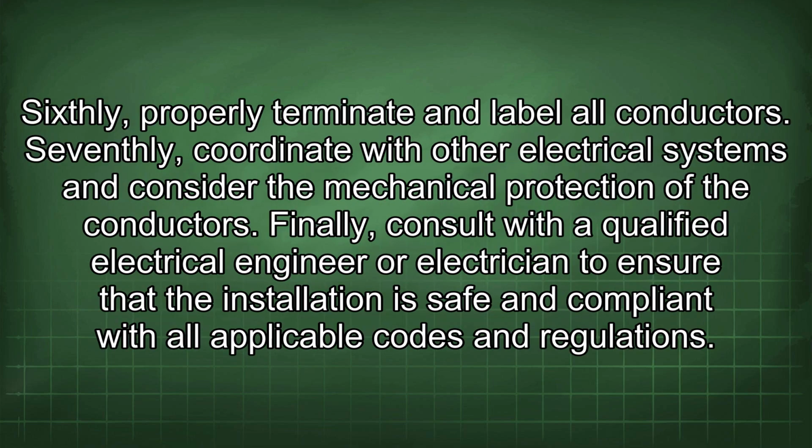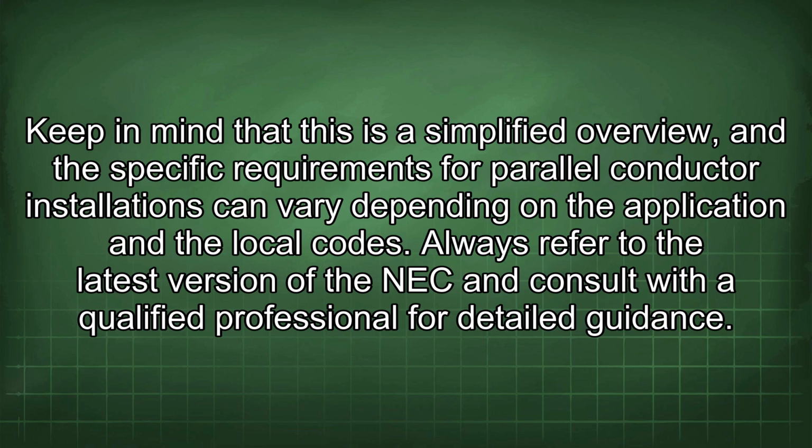Sixthly, properly terminate and label all conductors. Seventhly, coordinate with other electrical systems and consider the mechanical protection of the conductors. Finally, consult with a qualified electrical engineer or electrician to ensure that the installation is safe and compliant with all applicable codes and regulations. Keep in mind that this is a simplified overview, and the specific requirements for parallel conductor installations can vary depending on the application and the local codes. Always refer to the latest version of the NEC and consult with a qualified professional for detailed guidance.